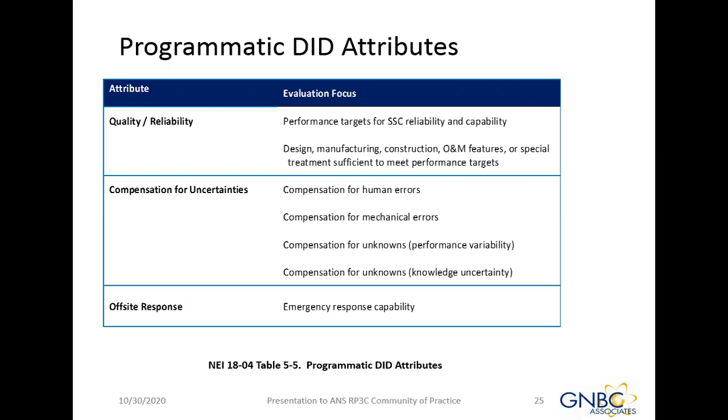This is also where you look at compensation for human errors and making sure that human reliability has been properly factored in, and that the human factors program for any safety-related actions that operators have to take have been properly addressed. You look at mechanical errors, you look both in failures or degradations of performance. This is an important component if you're using passive components, because passive components don't turn on or off, but they do have the potential to degrade and drift outside their operating design envelope.